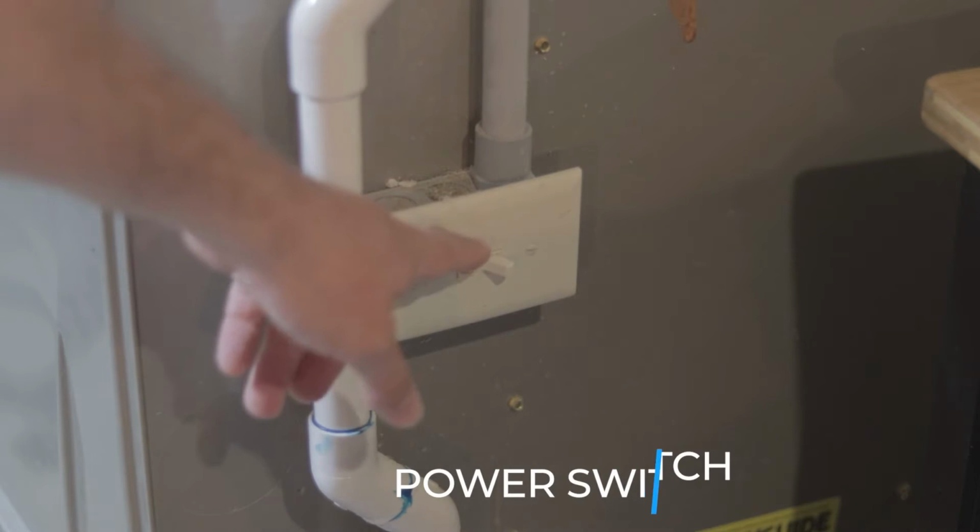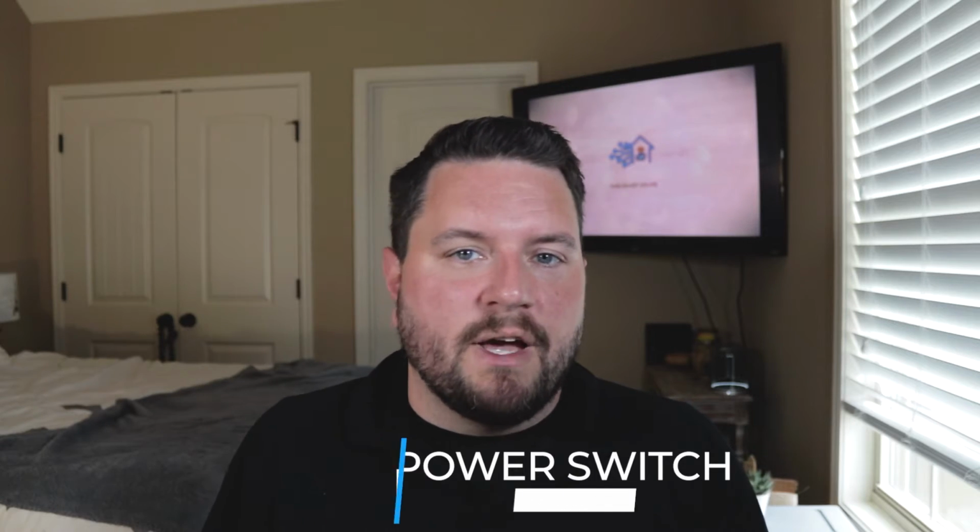Make sure the power switch is actually turned on the side of the HVAC. Most HVAC systems will have a power switch right on the side that can be flipped off if you're going to be doing service. Make sure that is in the on position.